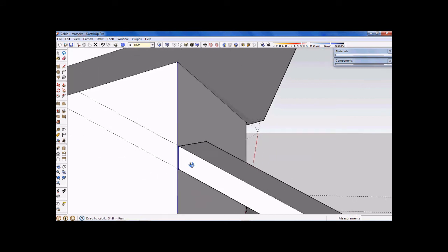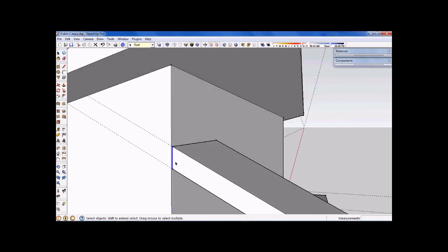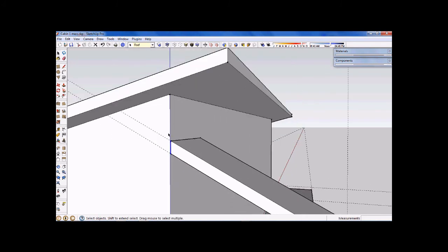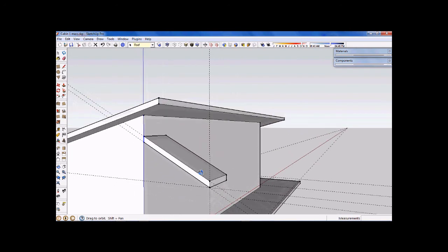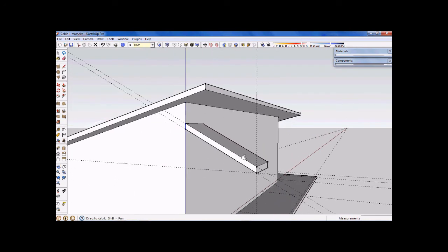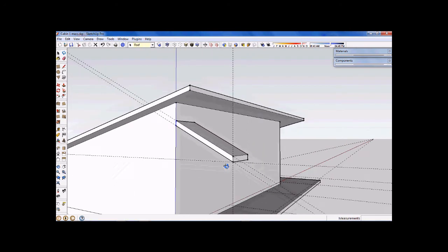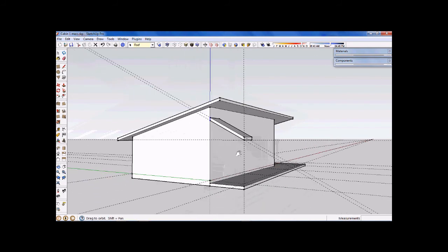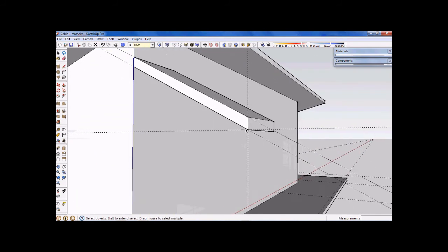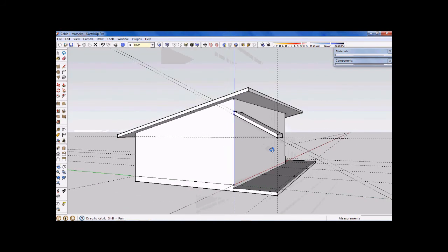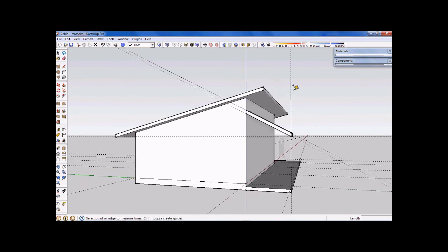So I've got this roof plane set up. I don't think I need any of those construction lines at the moment. We might do one more thing actually. We might extend this roof shape out another 150 millimeters, so we've got a bit of a 150 millimeter overhang. So I'll grab my tape measure once again, grab this construction line, pull out, orbit so you can make sure you are going in green axis direction, and when you do get the green axis direction, just type 150.